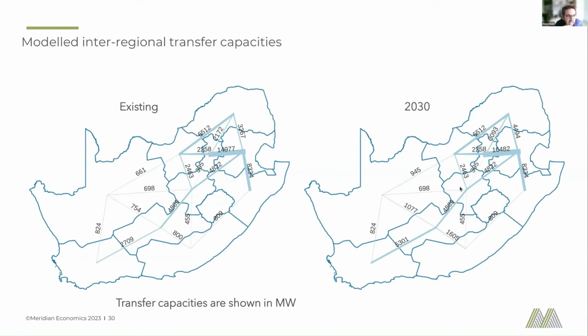So if we put this together, then how these might change over time. One thing that is not represented in here is if some of the lines on each end are doing VAR support, for example, and that would reduce some of the transfer capacity in megawatts. But then some of them might be compensated, which raises it again. So those two factors are kind of canceling each other out, but it might swing it one way or another. So at the moment, these are our calculations.